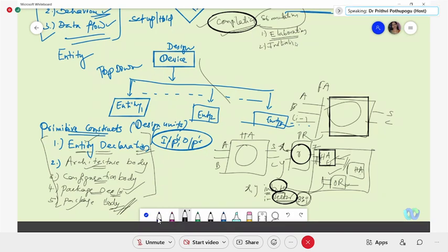Initialization is done in your simulator. Elaborate the netlist in your simulator. This segment, elaborate the netlist generated in your compilation segment, and that netlist will be initialized with values. Then the simulation will be done. These are the stages what completes your total designing using tool.